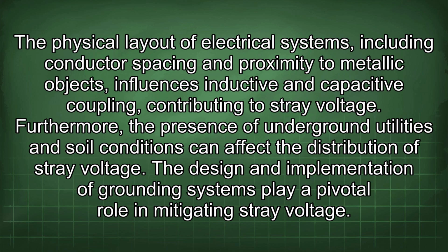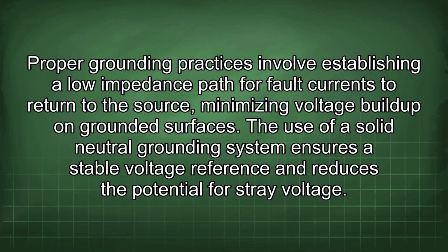The design and implementation of grounding systems play a pivotal role in mitigating stray voltage. Proper grounding practices involve establishing a low impedance path for fault currents to return to the source, minimizing voltage buildup on grounded surfaces. The use of a solid neutral grounding system ensures a stable voltage reference and reduces the potential for stray voltage.